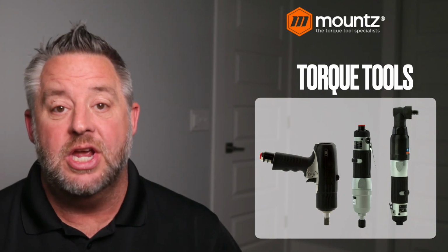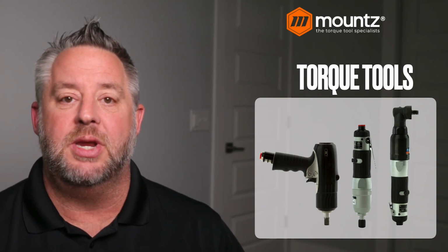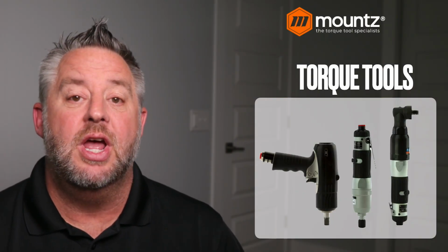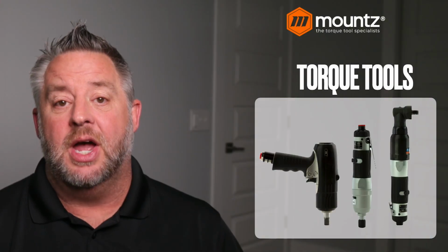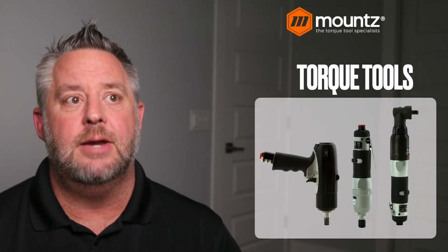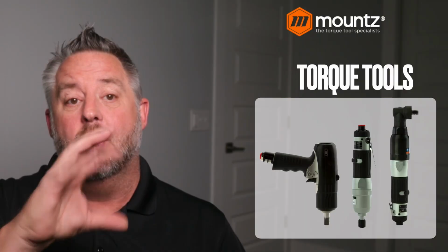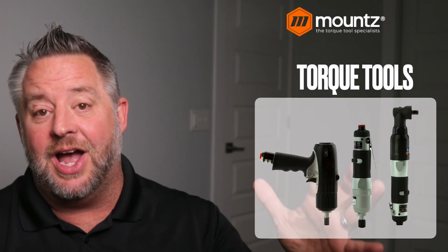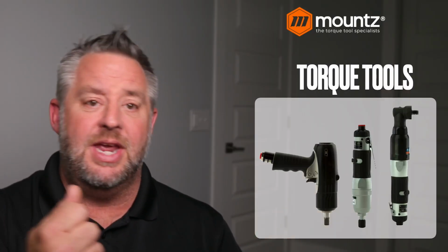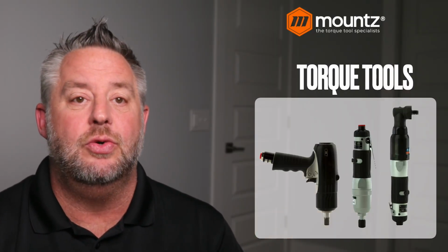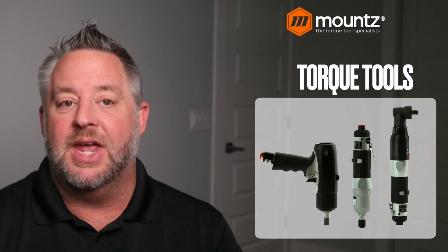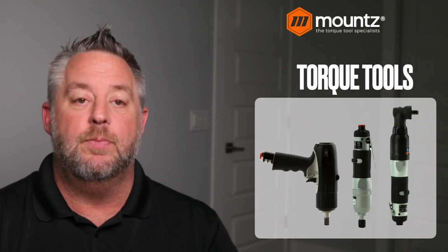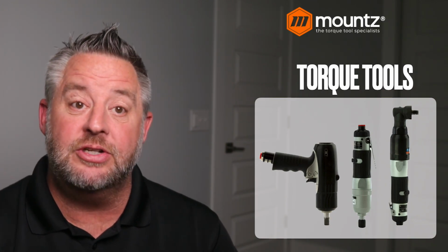And in some cases, if we use what would be considered a hydraulic pulse tool, it uses a special hydraulic clutch mechanism that's very similar to an impact style of tool, where it will hammer on a fastener. We can get very, very high torque values without much reaction when the tool shuts off. And so the hydraulic pulse tool is a good option for those types of applications.